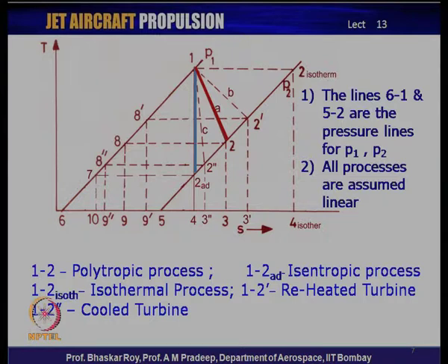As you will probably learn very soon, quite often many of the turbines are indeed subjected to cooling for lifing purposes, and hence those also have certain thermodynamic ramifications. So, these are the various obvious possibilities that could occur in an actual gas turbine of a jet engine, and we will see how these things actually affect the operation of the turbine.